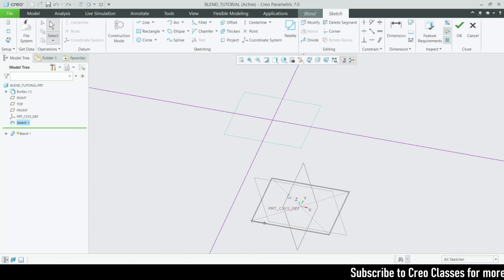The first one is, you can see the bottom sketch which we created before, our section 1, has been reflected on the new plane which we created. You can see it got traced, right? So we can directly use the project tool to project this, or else you can go for the line tool and draw a line on this existing profile.